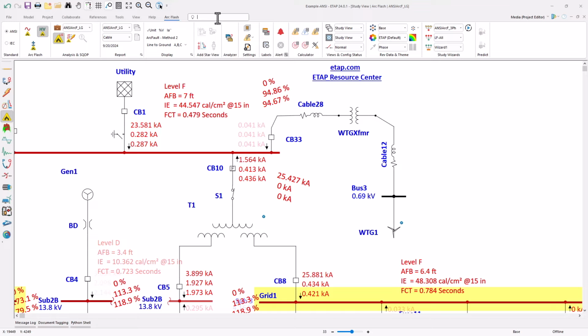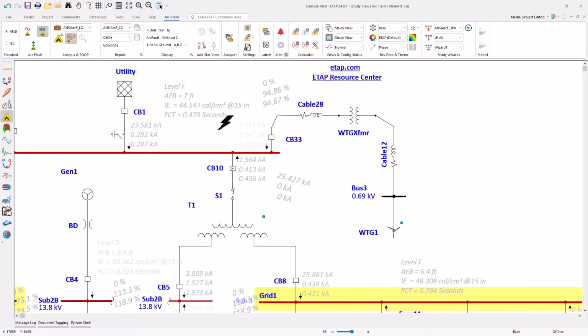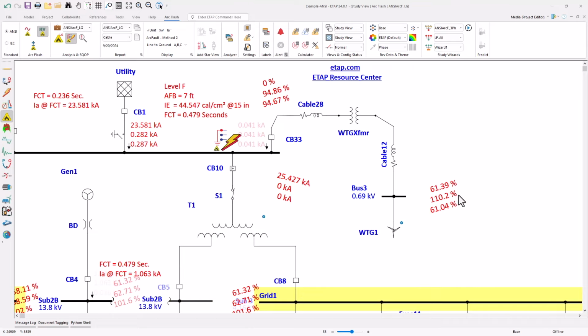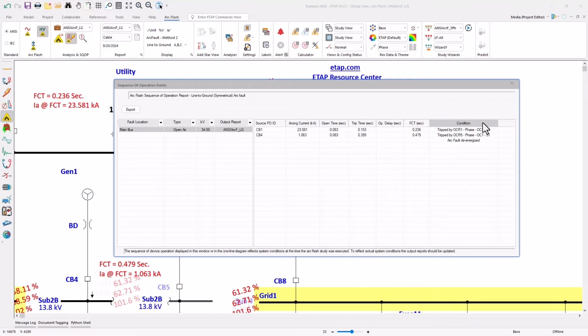For example, frequently used tools like fault insertion can be typed into the command section, and that would automatically trigger the fault insertion toolbar, and that would determine the overall sequence and the selectivity of the power system. Another useful feature is that the ETAP ribbon can be customized to have keyboard shortcuts that are used frequently, helping reduce clicks, and used according to the customer's convenience.